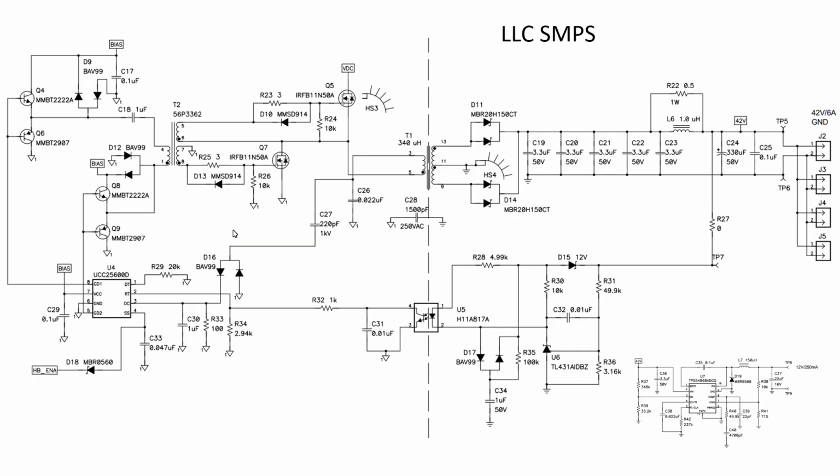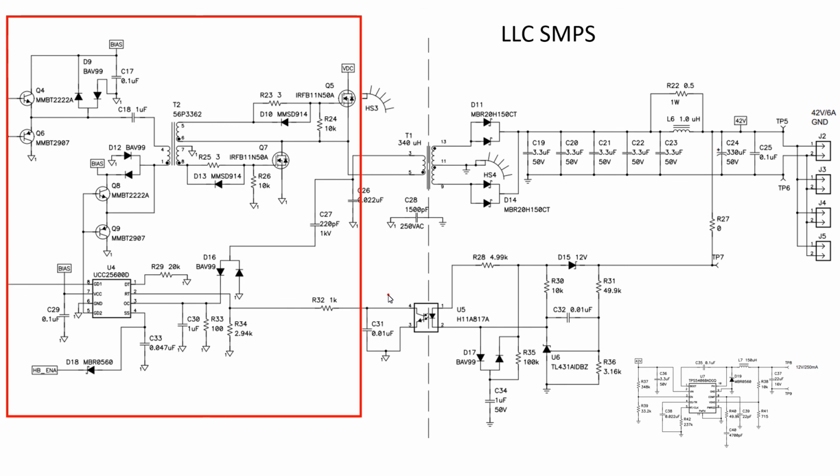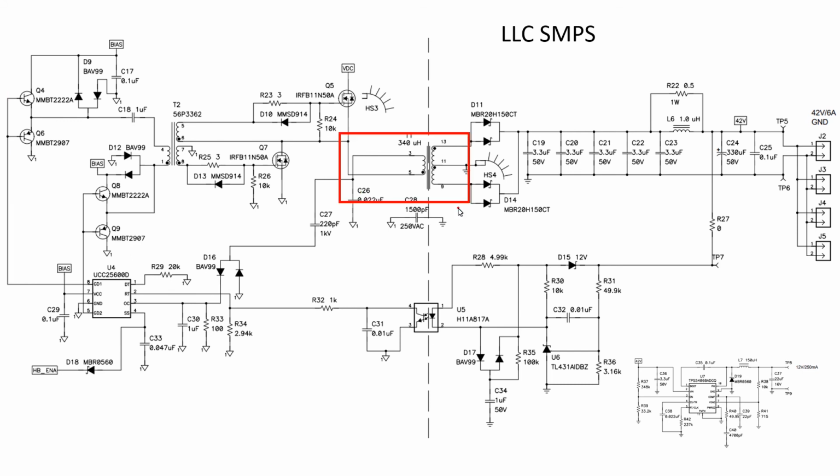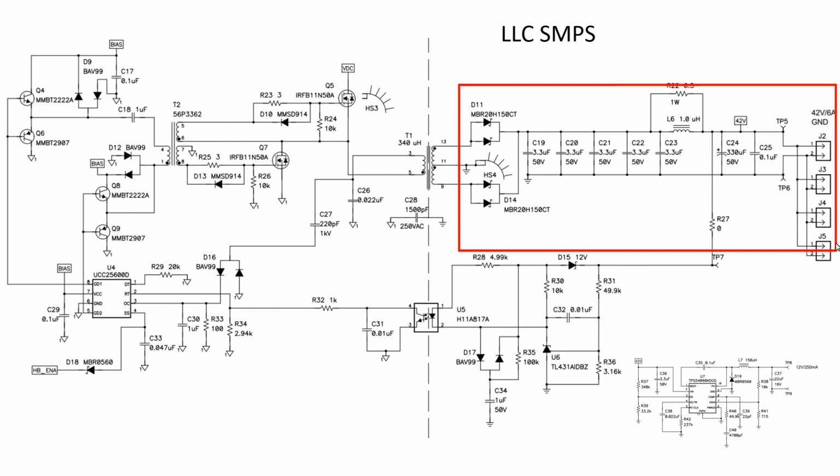There are real application schematics. From the left side, you can find a gate driver and components and low power transistors to drive the power switching stage. The main transformer with the leakage inductivity, transformer inductivity, and resonance capacitor. All the complexity of design is hidden in this part. Secondary winding and low losses special rectification diodes. Physical appearance looks similar to power MOSFETs, and for high power solutions, rectifier diodes are placed on a heatsink.